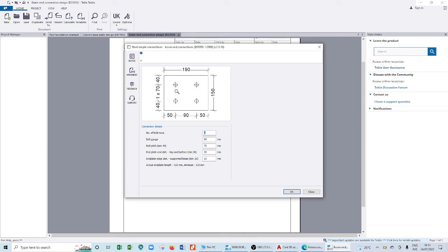I don't need to create two bolts so close to each other. Because at one point, the other one is where I move, the plate will still also be there. So I can give them that spacing. So when you see here, it's showing you 40 up, 40 down, and it's specifying here a 70. So that's the spacing between the two. So meaning in overall you're using your plate to be 150.